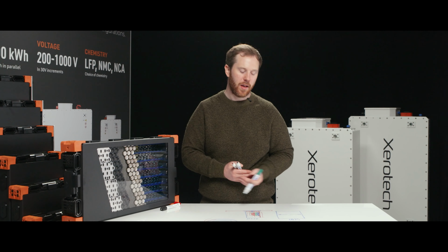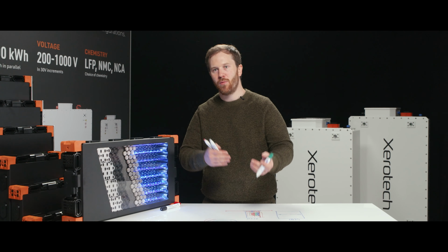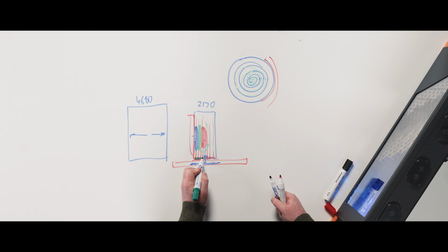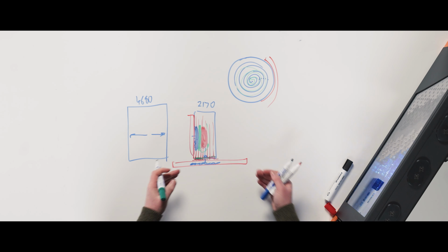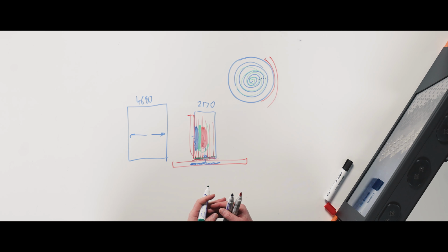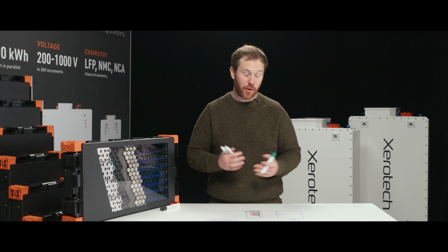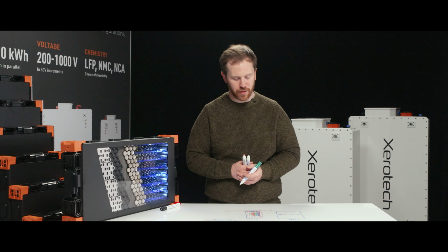So those of you in the industry would have heard of tabless battery cells, an invention Tesla and many others have deployed. What they're trying to do there is decrease the thermal resistance at the bottom of the cell to promote the heat transfer out of it, to make them more effective for sidewall cooling. But even still, an important fact that I point out even to my own engineers is that when you take the Tesla 4680 tabless design, they're still doing sidewall cooling. Now that might be for manufacturing reasons as opposed to performance reasons, but it's an interesting point nonetheless.